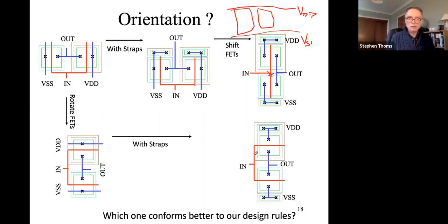Now, the polysilicon is chosen to be good at being a gate. It's chosen for its work function and so on. It's not really chosen as the material with the greatest conductivity. So here, when you've got a longer length of polysilicon, you've got more resistance. You've also got more capacitance because there's always stray capacitance with these lengths of connections. More resistance, more capacitance, more parasitics, slower. So this one looks like the better design.